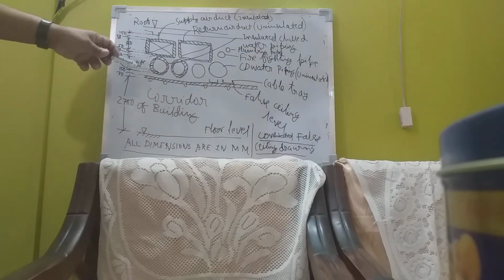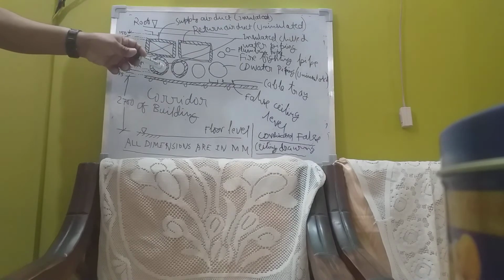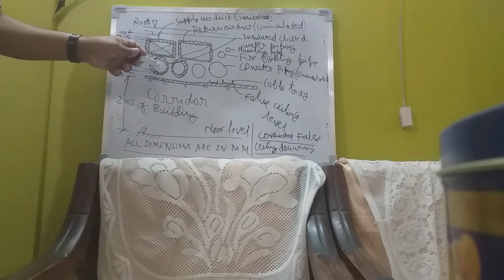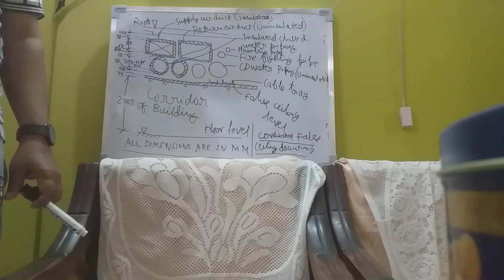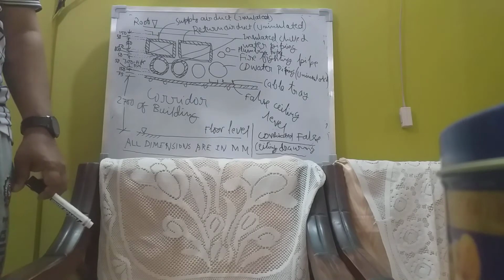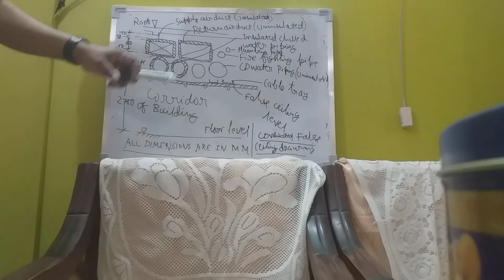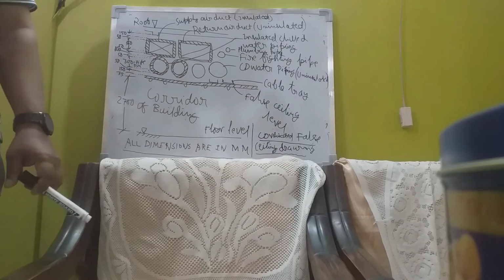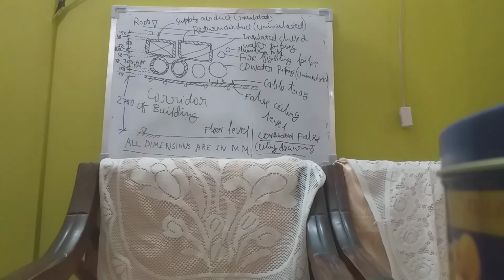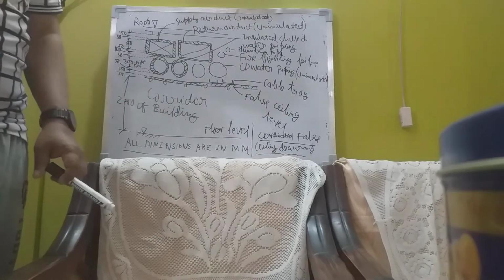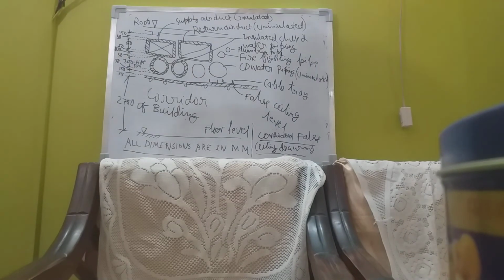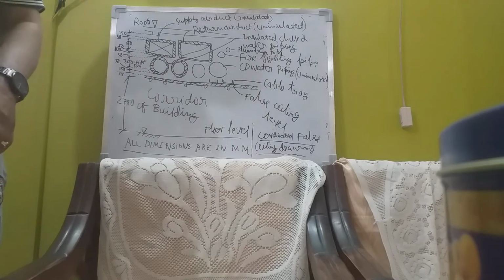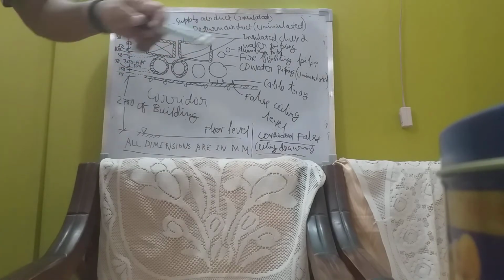See, I have taken a diameter of 300, but at the beginning it may become 3000 mm, the diameter of the chilled water pipe in case of a big building. 3000 mm, you understand, is around 10 feet, the diameter of the pipe of HVAC. That means 10 feet plus insulation plus supply air duct, all these things will go. So the first job the architect does in building coordination is to call for the HVAC drawing. First he fits the HVAC drawing, then he fits the other services.